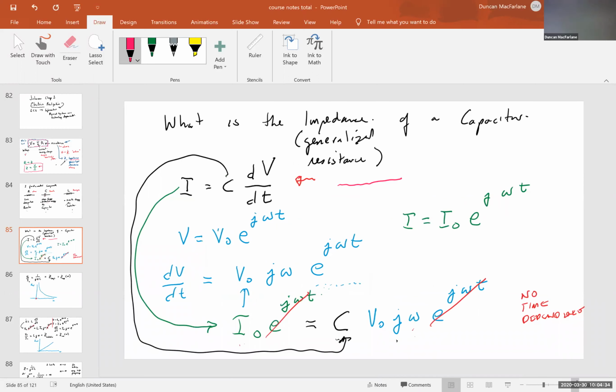One thing that, at the risk of confusing you, is we had the fundamental law Q is equal to CV. So the capacitance is defined as the storage of charge and the voltage that charge produces, and then the energy. If you want to think about it this way, make the units work out right and the geometries work out right. That's all the geometry and all the units and the materials are described by the C. And so then if you take the derivative of both sides, d by dt of both sides, if C is a constant, then you get this, our starting point.